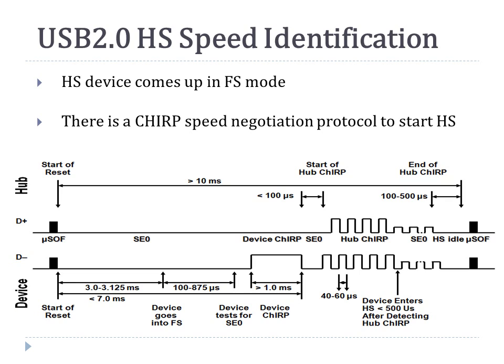So what's happening is, once the device gets connected, the host drives a reset. That is, both lines are held to 0, and any high-speed capable device will pull up the D plus line, drive a K-state on the D plus line, and this indicates to the host that this is high speed capable. Now if the host is also high speed capable, it returns a series of KJ patterns here, and then both the host and device are in the high speed mode. And you see here that the swing changes from 3.3 volts to 440 or 400 millivolts. This is because of the change in the terminations in the drivers.